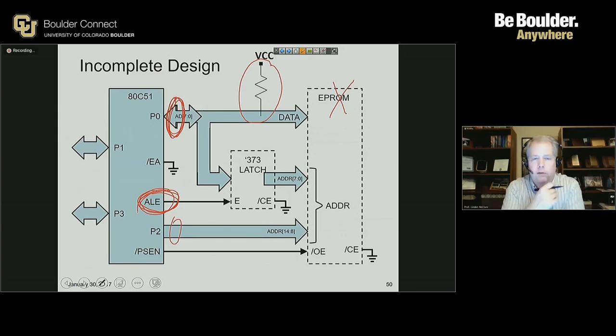Okay, are there any questions about this concept? It's important that you understand the general system issues here and how we can address them, and how we can know that by taking a scope with passive probes, we can actually understand what's happening in the circuit, even if we're not allowed to probe right at the crystal pins themselves. Any questions?